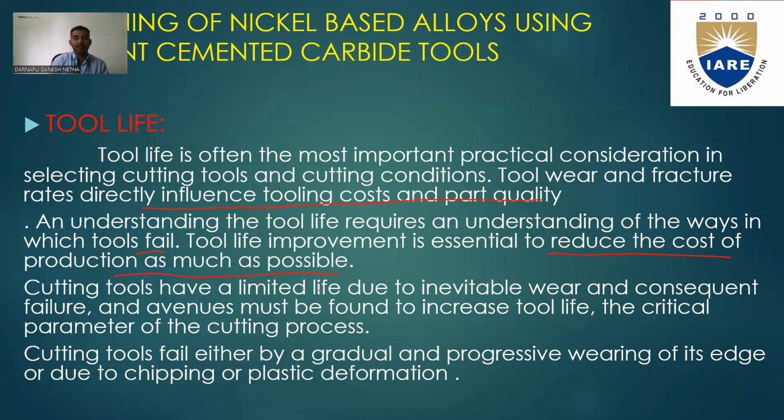Cutting tools have a limited life due to inevitable wear and failure. Advances must be found that increase tool life, a crucial parameter of the cutting process. The cutting tool fails either by gradual and progressive wear of its edges, or by chipping or plastic deformation. How is the tool life going to be increased?